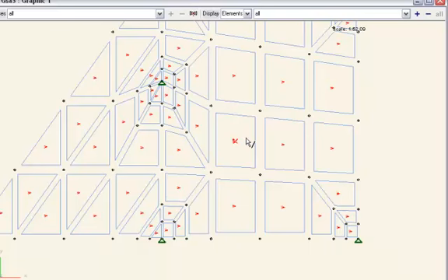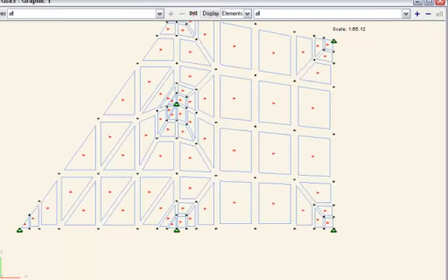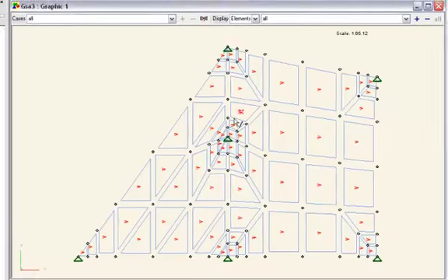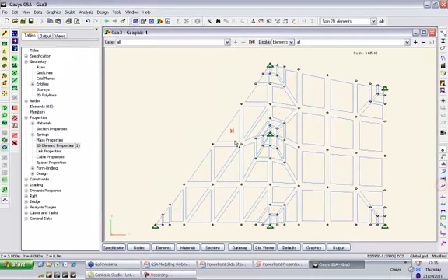Now these are all currently quad 4s and triangle 3s, what we call linear elements. But using the new MITC linear elements, these can be okay now. They didn't used to be. You used to get a lot of hourglassing problems, but you can change all these elements.